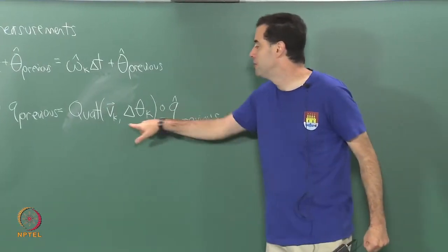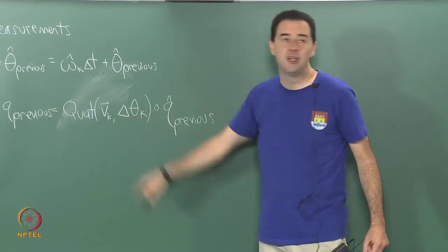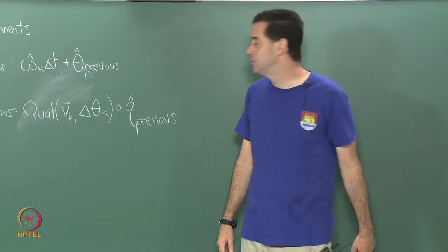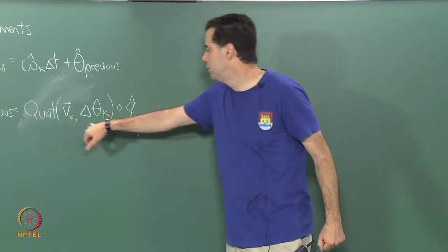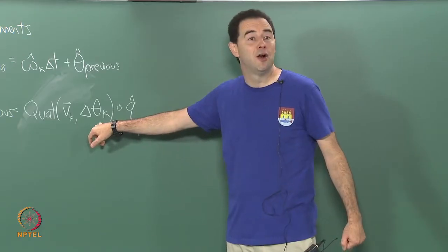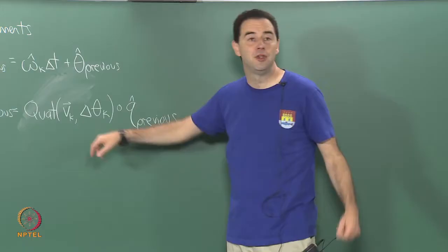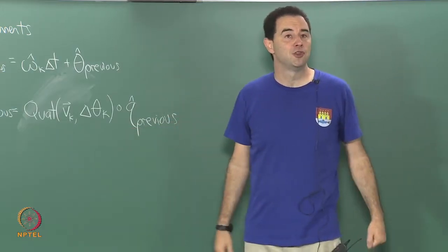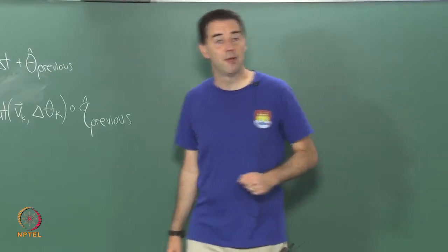And remember, these two parameters come directly from the gyro reading. If you normalize the omega x, omega y, and omega z components, you get the axis of rotation, and the magnitude of that original omega x, omega y, omega z vector gives you the total amount of rotational change estimated for that 1 millisecond. You've got to remember that.